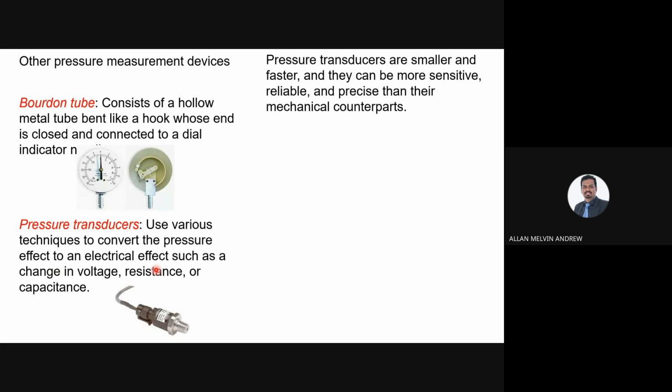Normally, what the sensors do is receive input from the environment, from the human, or from the mechanical system, and convert it into an electrical effect. So it will have a change of voltage, change of resistance, or capacitance. Normally these three. Based on that, we get a digital value which we can use in our microcontrollers or in our computation in the computer.